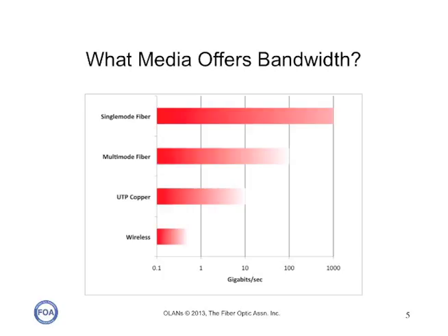Copper wire is simply limited by the physics of sending electrical systems over twisted pairs of wire. Multimode fiber, which you'll learn what that means in a second, gives you another 10 times more bandwidth than copper, but single mode fiber gives you almost unlimited bandwidth, more than a terabit per second.